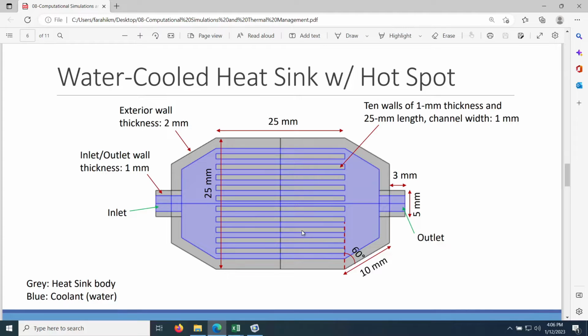Now, what I want to do is to modify this heatsink, and instead of having channels all across the heatsink, have fins where the hotspot is, because fins or pins will create more cross-section area that's good for convection heat transfer through water. And then we can probably put these results together in a graph and see how the two heat sinks perform.